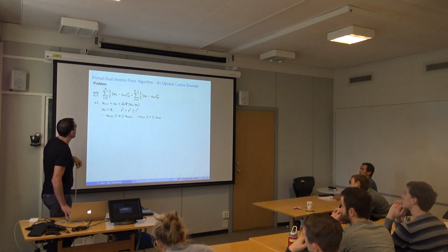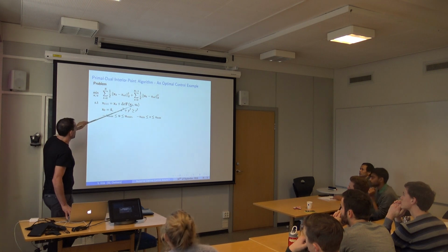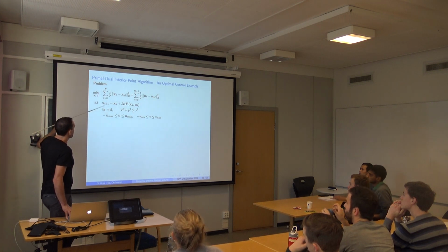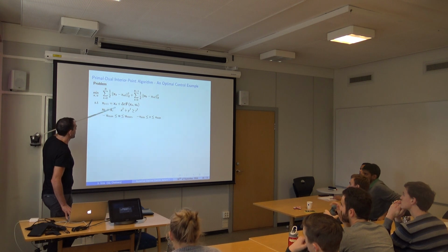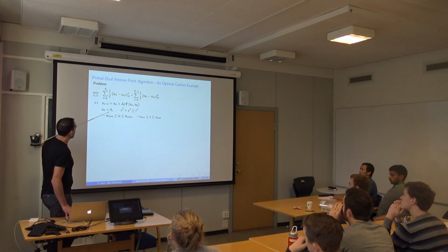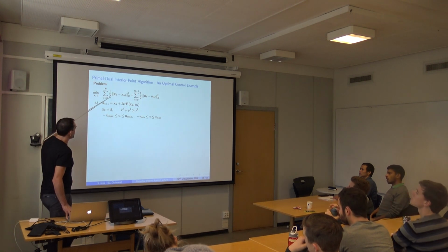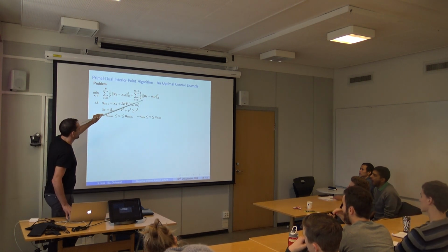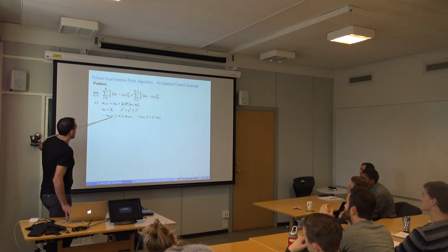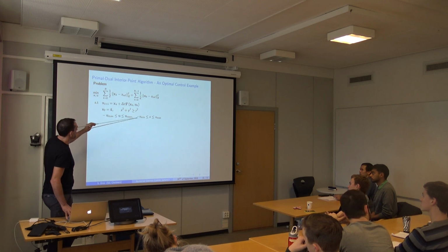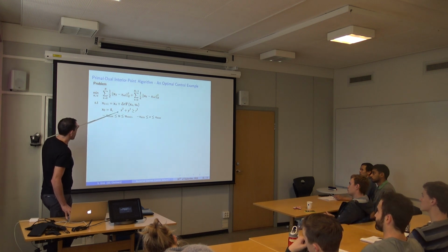Okay, you can make some examples. Yeah, that's actually optimal control. That would be MPC-like stuff. I would have an ODE given by F. Here I would write an Euler integrator, why not? Some imposed initial conditions. I have some quadratic penalty, so I want my states to meet some reference. I have some bounds on my states and inputs, and then I throw in some non-convex inequality constraint in the problem.